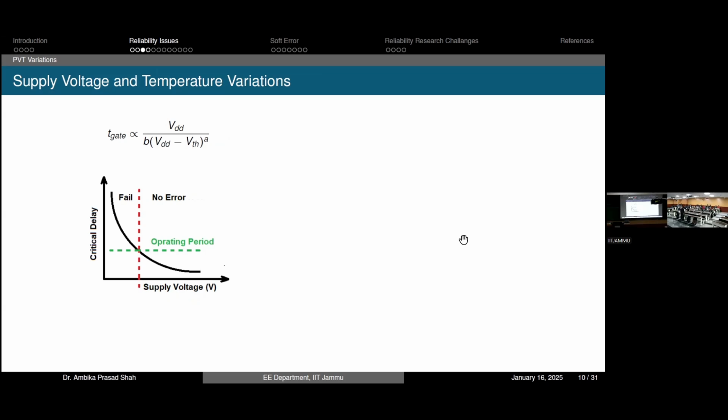So this is available actually. Fine. So I was talking about this supply voltage. If I have a higher supply voltage, definitely the delay will be less and the power will be higher, and vice versa.